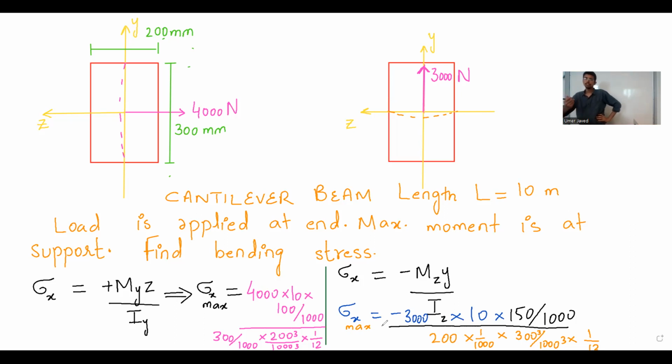You got a negative value for the second one because I am selecting a positive value of y for the right case, and exactly right. So on the upper surfaces, upper fibers, or the top upper fiber, you have compressive stress. And for the left one, I substituted z value of whatever. So you can see for the first case, to the left side, you have fibers that are expanding. In the positive z axis, the fibers are expanding. Should I continue? I will wait for our students.